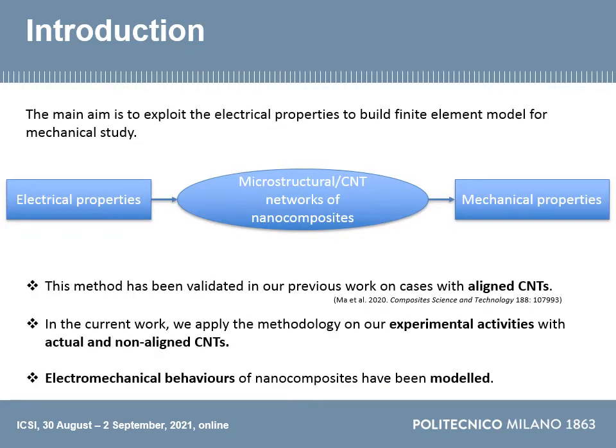The basic insights of the current solution are presented in this slide. As we know, the microstructure, or the CNT networks inside the polymer materials, determines both the electric properties and the mechanical ones of the nanocomposites. So we think that maybe it is possible to get the microstructure information according to the electric properties of the nanocomposites, and then this microstructure information can be used for the mechanical modeling process.